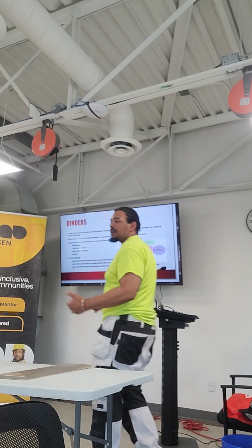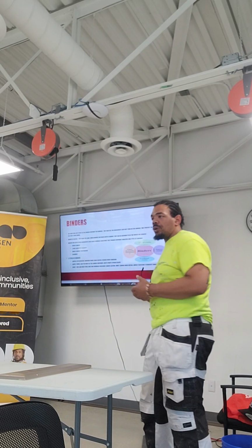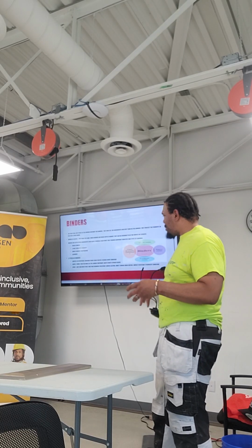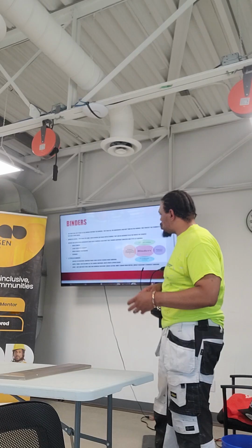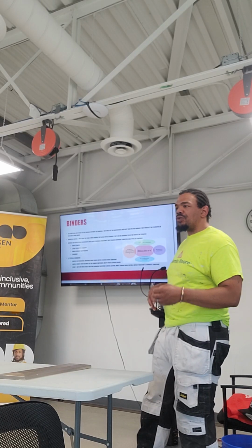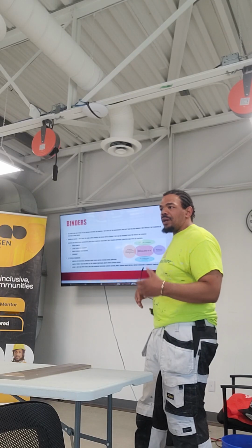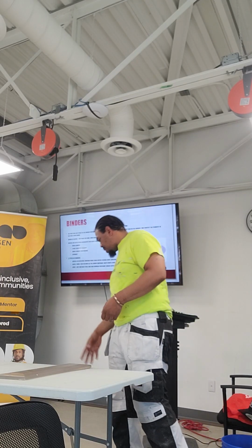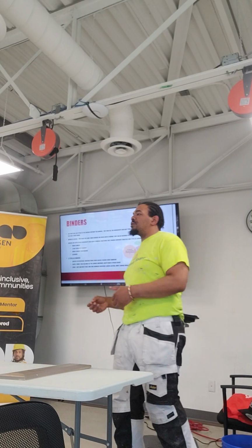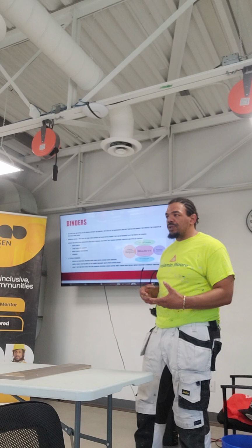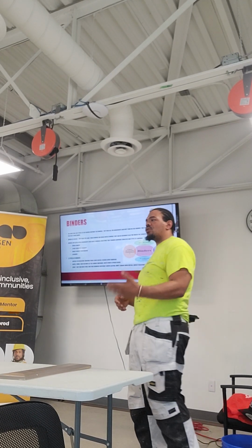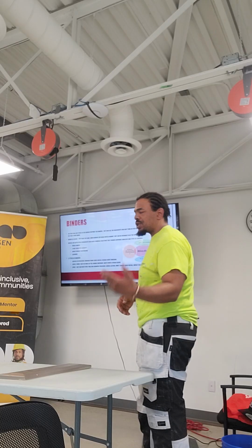An epoxy binder is one of the strongest binders in the world. They use all three of these to make paints, but the epoxy binder tends to be stronger, it's more chemical resistant, and it lasts longer. It's also a lot more resistant to scratching and marring. An epoxy binder, which you would use in floors, is what you would see in certain clear coats. They have certain water-based epoxies that are reinforced with these epoxy binders, so the material is a lot more chemical resistant and a lot stronger against marring and scratching.